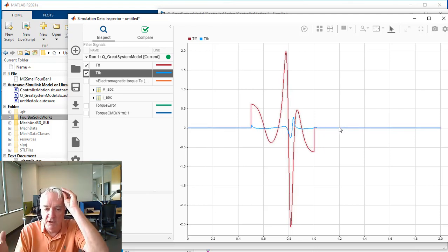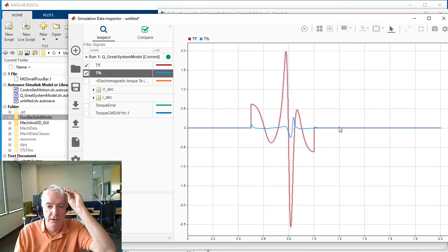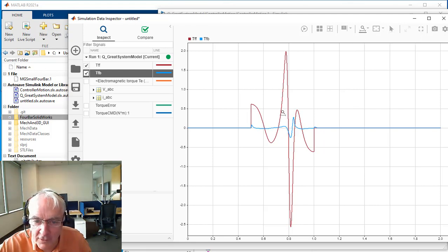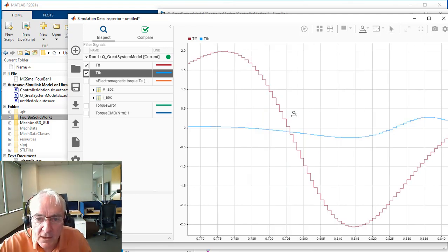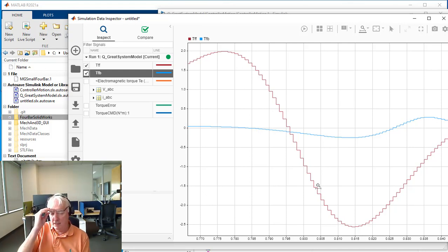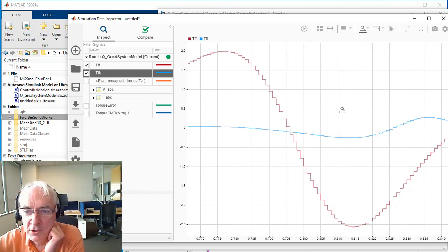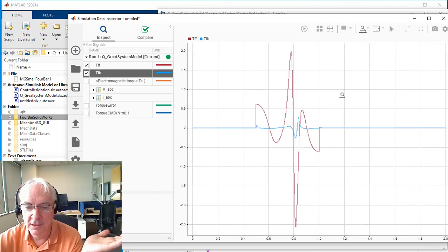In simulation, that feedback was almost zero compared to the feed forward, but here we're seeing it's a little bit bigger. I studied that a little bit this morning. At first I was bothered, but then I thought about it: we're operating our control at 1,000 hertz, and for those really steep gradients, you can make the case that an update rate of 0.001 seconds is not nearly enough to capture that transition without it having a jagged, staircase kind of look to it. Without too much further analysis, I'm going to say that that's the issue.